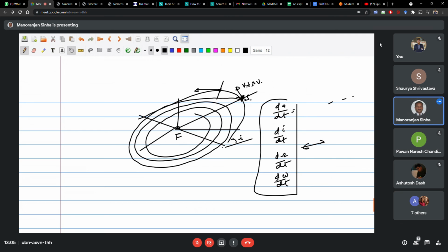The energy decay results in the change. For changing the argument of perigee, you need to give impulse, and while this is changing, your orbit becomes an oscillating orbit. It's continuously changing. It's no longer a Keplerian orbit. The plane will not change. That means capital omega and i are not changing. Your a is changing, e is changing. For argument of perigee to change, you require impulse at certain other points so that it changes further. Otherwise the symmetry will be maintained.